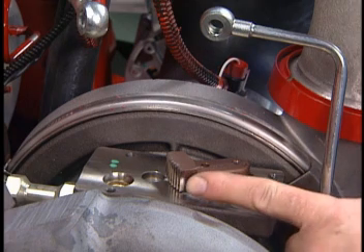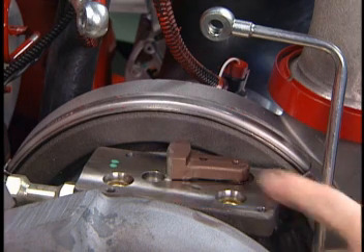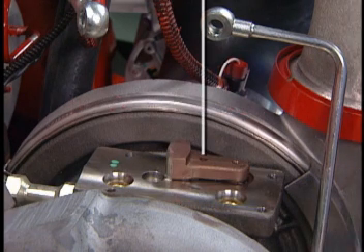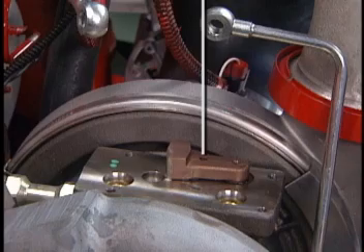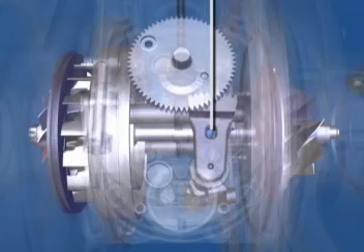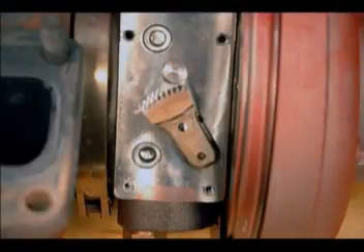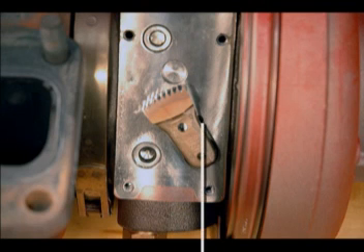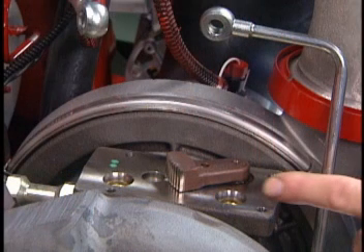To determine this, slide the gear to the compressor housing, align the holes in the sector gear and the turbo housing. This will indicate full travel in that direction. Rotate the sector gear to the turbine housing and half of the alignment hole should appear at the side of the sector gear. If the sector gear does not go through the full range of motion, or the sector gear requires excessive force to move by hand, replace the turbocharger.